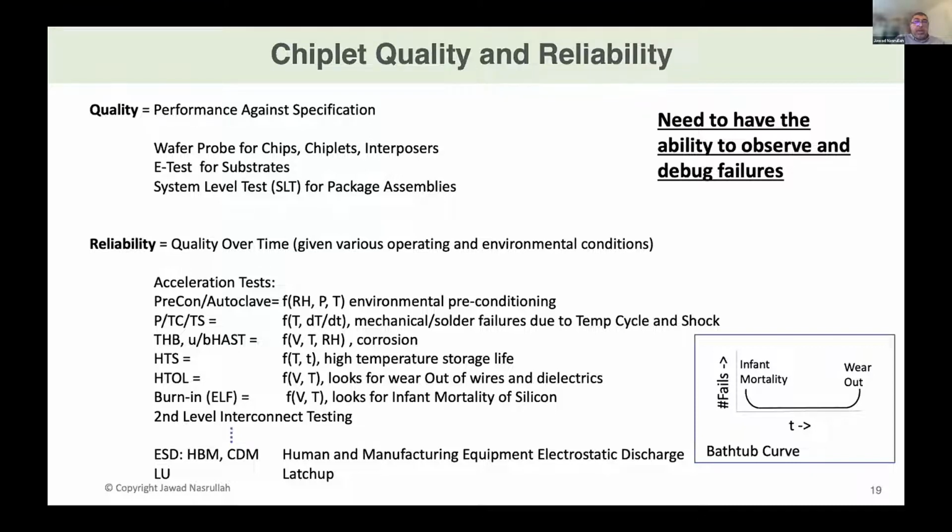So one challenge I'll say is, if you are using a backend factory to assemble the final product, there will be multiple reflows of some of these components. And those reflows start to have some really strange problems in certain cases. So we have to start thinking about those kinds of manufacturing defects.